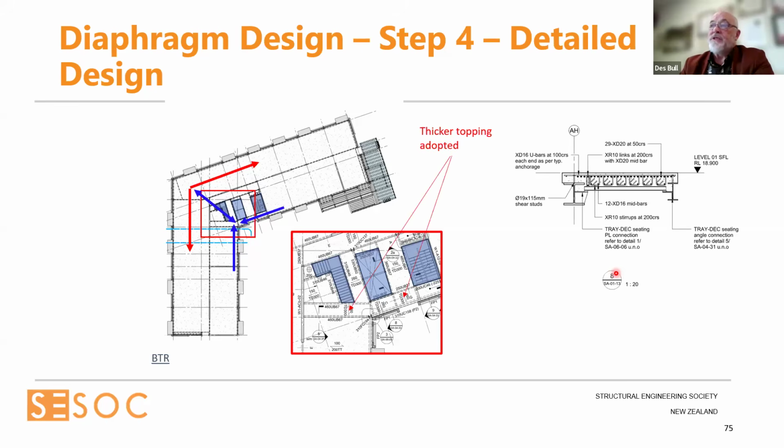So what they came up with is those particular parts of the floor, they thickened up and turned into columns. So that thickened floor can handle the tension and compression in that reduced section. That's the sort of detailing that you're going to have to employ when you've got these unusual architectural demands.